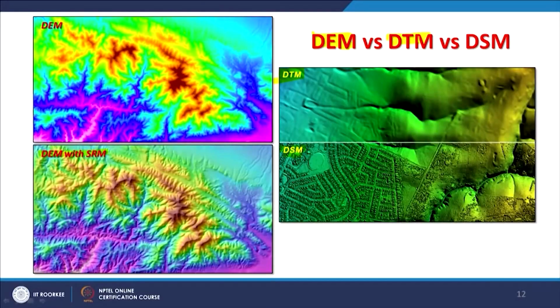Sometimes people use terrain when it is related to the real elevation, then we can call it either DEM or DTM. But as you know, DEM has become a generic word, so this E value can be any other value. Therefore, a new term has been introduced: whenever we say DTM, it means elevation, and the cell value is an elevation value.